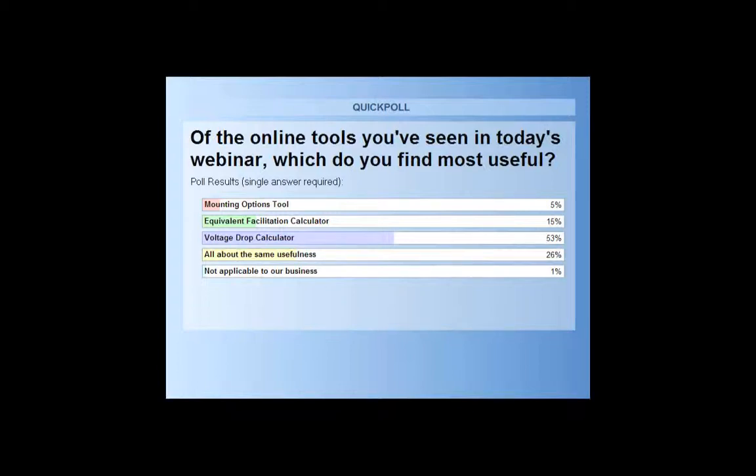Krista, the next one's a kind of a specific question. Some NAC boosters allow up to 2 amps for each of 4 circuits, but limit overall output to 6 amps. Is there any way to make sure you don't exceed the booster's overall output limit other than by adding the circuit current by hand?